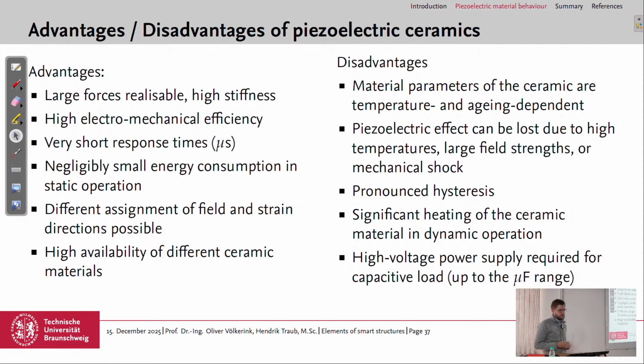And with this, we come to advantages and disadvantages of the piezoelectric ceramics. So we can achieve large forces. We have a comparably high stiffness, a high efficiency of the material, and also very short response times, so we can use it for dynamic applications.